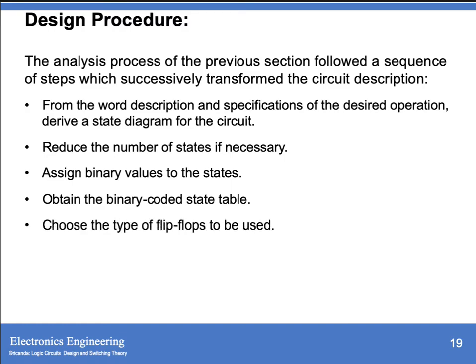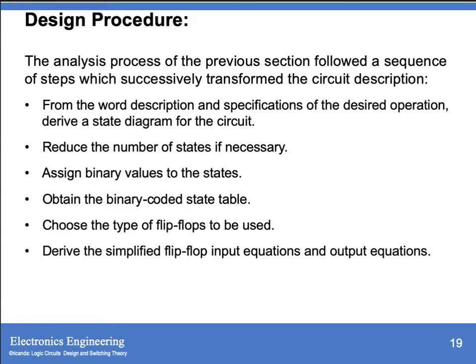Then you have to choose what type of flip-flops we are going to use for your sequential circuit, and derive the simplified flip-flop input equation and output equation. After that, using Boolean algebra or the map method, you have your simplified equation, then you can do your logic diagram.